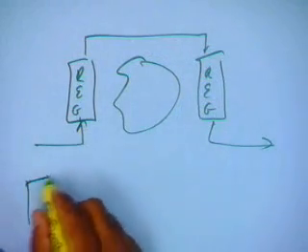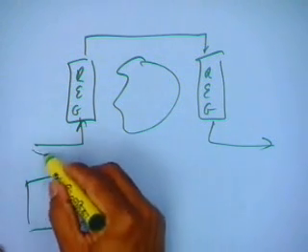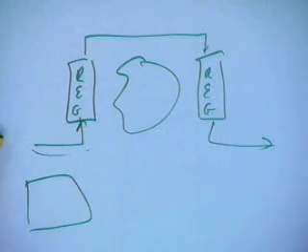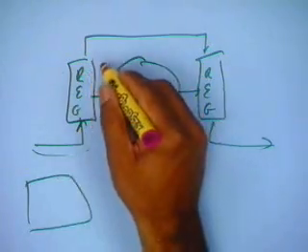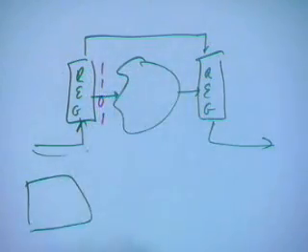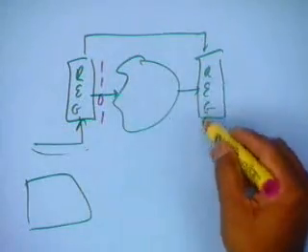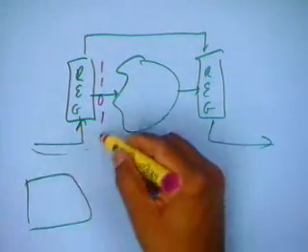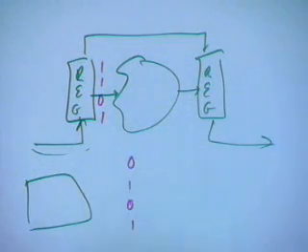So, my test inputs are stored somewhere. It could be of course off the chip or it could be on chip. That's a difference, it could be coming from the disk. I will shift in a test vector into these registers. By serially I will shift in and I will get, let us say, 1101. This is the test. I will apply the test, get the result over here, and then serially shift out, and then serially shift in the next test vector, which could be 0101. So, I will do that one.